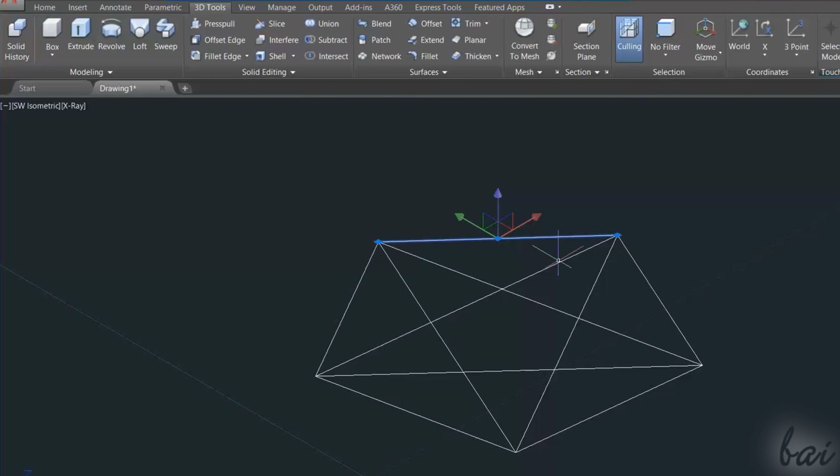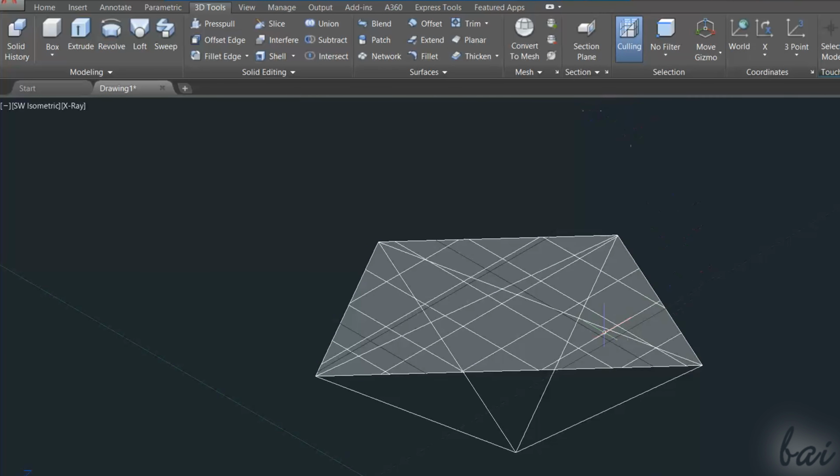When using the Planar Surface tool, the surface created spreads over everything until it meets its selected boundaries. To regulate the surface extension, you may need to use the Trim and Untrim tools inside the Surfaces section. The Trim tool is used to cut parts of the surface that meets other boundaries.